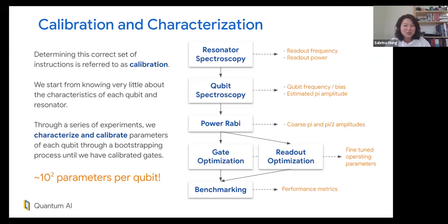Another thing that isn't quite classical is that our superconducting qubits are fabricated on these silicon wafers. And so, for example, there are defects that these qubits can actually couple to, which we often will just call two-level systems as a blanket term. And these two-level systems can also fluctuate with time, which means that the qubit might have been isolated and not coupled to anything for the whole day that you were calibrating the device. And the next day, a two-level system rolls into town, and you have to now deal with the emergence of that. And I'll actually talk a little bit about how we deal with that.